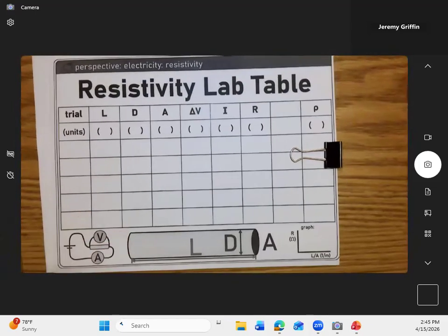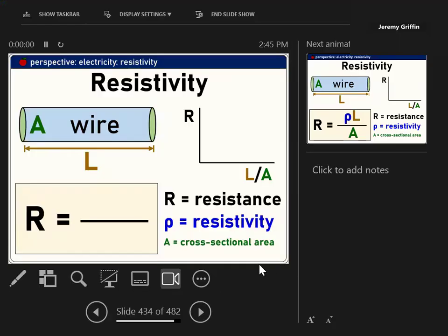So same thing I said yesterday, but maybe a little faster. Sorry, it's projected weird. If you have a wire, do you guys think that electricity travels differently through a copper wire compared to aluminum wire? I'm told copper is a little better, but the trade-off is it's a little more expensive, right? But it doesn't heat up as much. It's not as lossy. So the property we're looking at has to be some material property, right? And that material property is called resistivity.